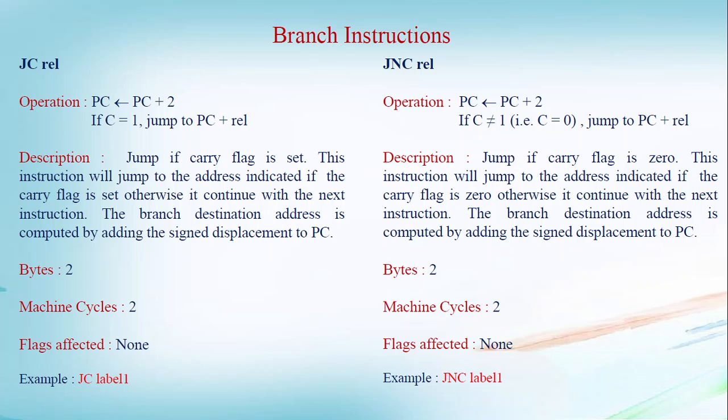Similarly, there is the JNC instruction. Jump if the carry flag is 0. Otherwise, it will continue with the next instruction. It requires 2 bytes and 2 machine cycles. No flag is affected. Example, JNC label1.